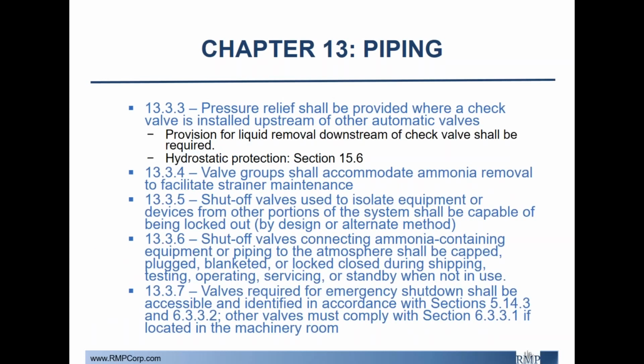Next section is Chapter 13, Section 13.3.3, which talks about pressure relief being provided where a check valve is installed upstream of other automatic valves. There's a provision for liquid removal downstream of the check valve that was also required. And it's also important to take into consideration hydrostatic protection, which will be covered in a lot more detail in Chapter 15, which covers overpressure protection devices.